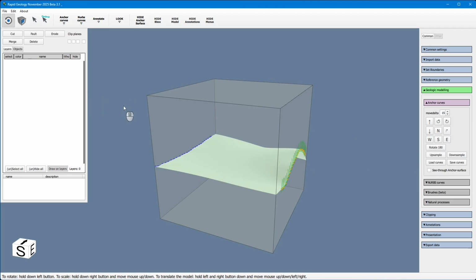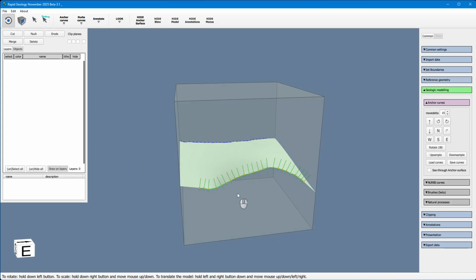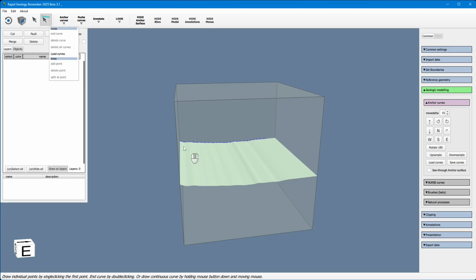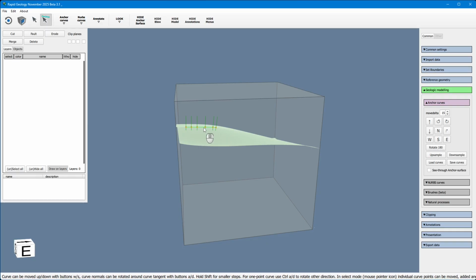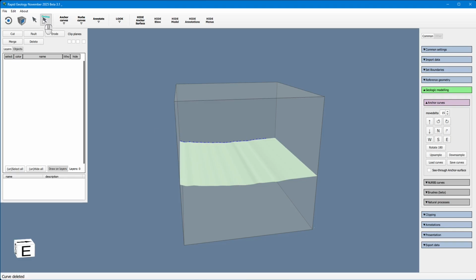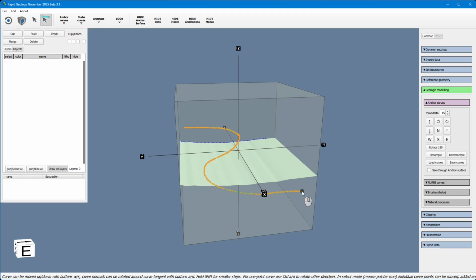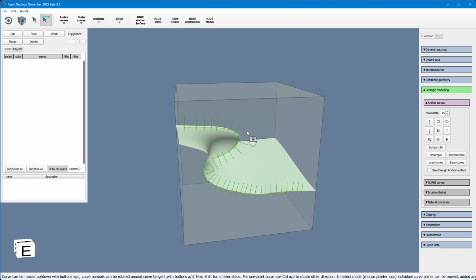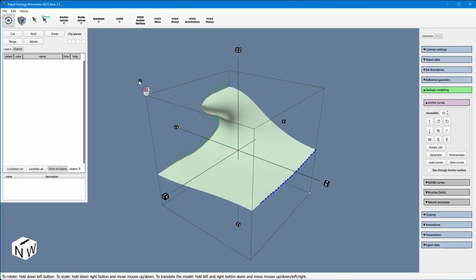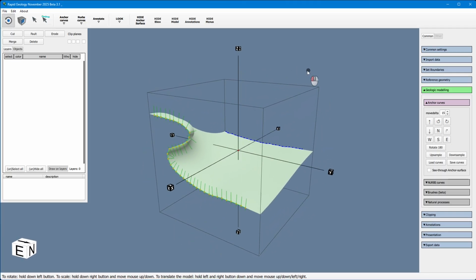The software tries to avoid this problem by working such that when you start drawing, the first normals of the first 2 segments point upwards. And then after that, they continue to point in a coherent way. What I mean by coherent is that if you start like this, and then you go down and up like this, then they point upwards here, then downwards, and then upwards again, so that you get this shape, which you sort of should expect.